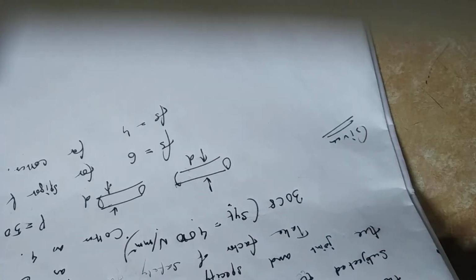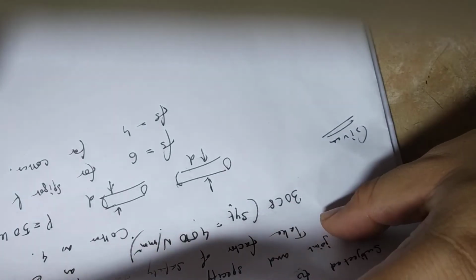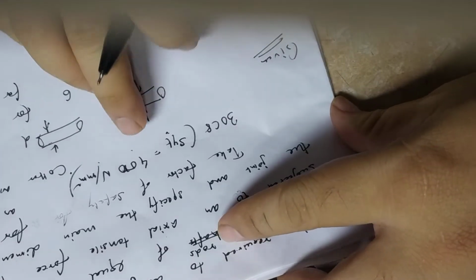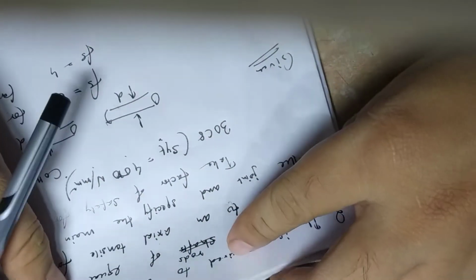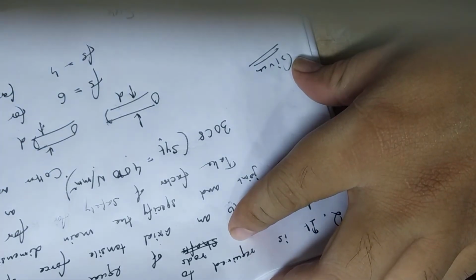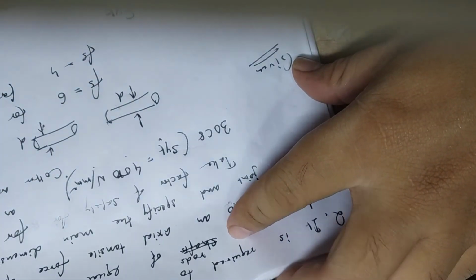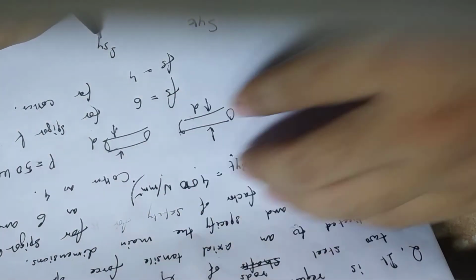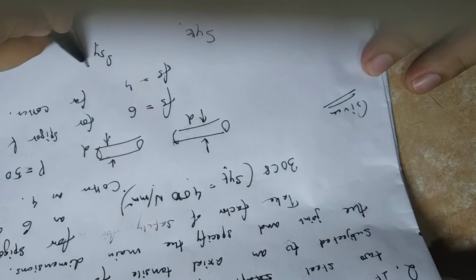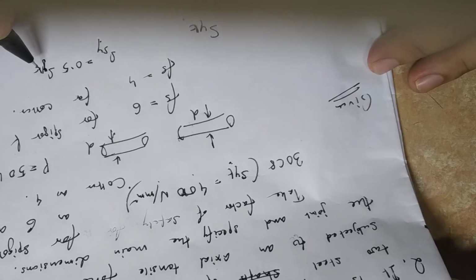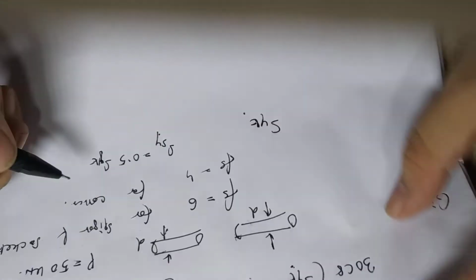One thing that is not given: in general there is a theory that you'll learn later. If SYT, the yield strength in tension, is given, to find SSY, the yield strength in shear, we use a relationship given by a theory called the maximum shear stress theory.